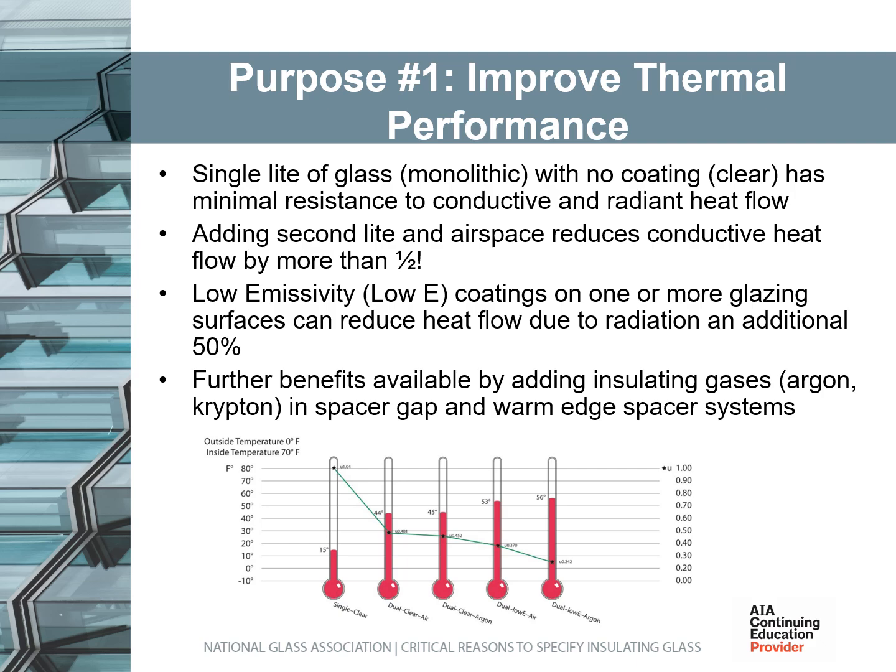Low emissivity coatings are used to limit radiant heat energy that passes through the glass. A thin coating on the surface of the glass is used to reflect infrared light or heat energy while still letting visible light through the glass. Different coatings will be used in different climates to get the desired effect. To increase the IG efficiency after adding lights of glass and coating, using warm edge spacer systems and substituting air with other less conductive inert gases such as argon or krypton can be incorporated.